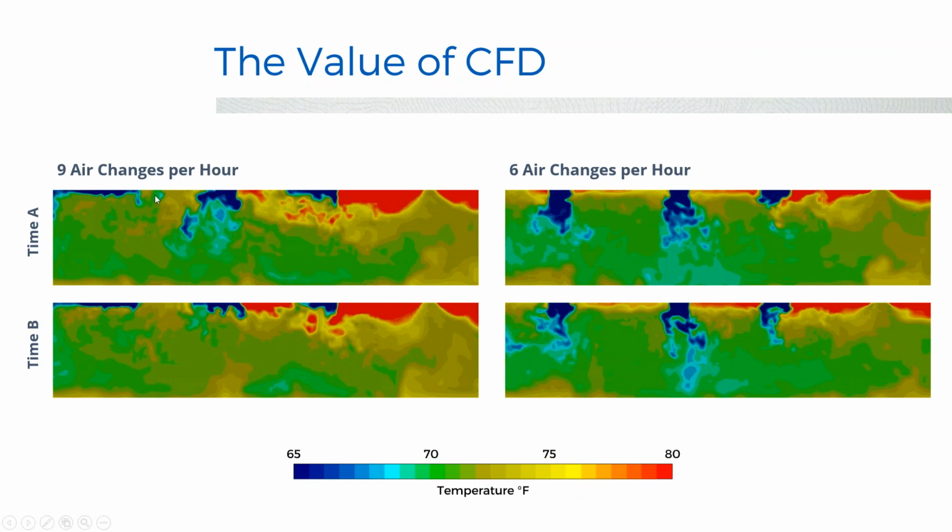These are swirl diffusers. You can see in this image they're going across the ceiling as you would expect from manufacturer data. An important thing to recognize about manufacturer data that you get on these diffuser characteristics is that most of the values you receive are from isothermal conditions, meaning that the air leaving the diffuser is at the same temperature as the air in the room.